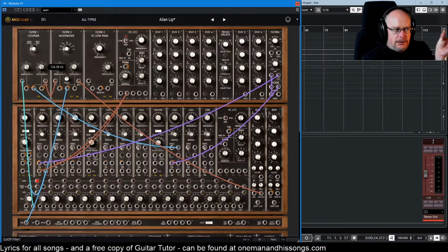So it's just like a moving slider of what it's going to throw away. And that frequency there is going to be modulated down, as it happens because it's a negative number, by this sine wave. So it's basically going to do this kind of thing. Move the section of sound that's going to be thrown away by this filter.